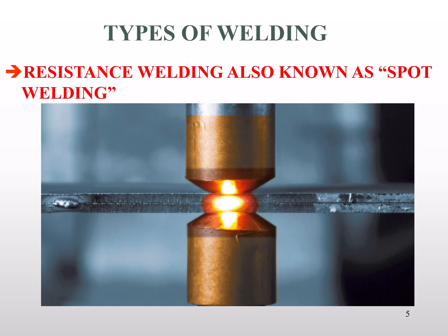Resistance welding, also known as spot welding, is a major manufacturing method. The two electrodes you see in the picture are there to flow a very high amperage current. Because the metal itself provides more resistance to flow than the electrodes do, the byproduct of resistance is heat. And in this case, the current flow heats the material to the point that it reaches that molten state.